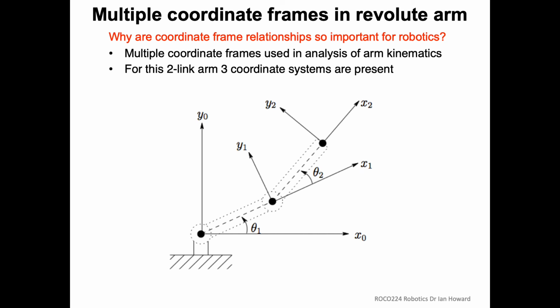And all we have to do is we say, look, here we've got a 2-link arm. We can define the frame at the coordinate base of the robot, and that's the thing we really care about. If we know that, then we're well on the way to working out how to use the thing, and certainly in terms of forward kinematics. So we want to know where the endpoint is in the frame at the base.